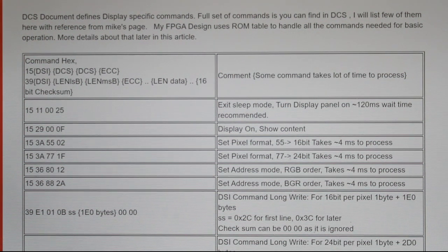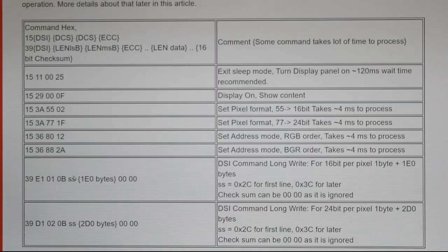But please make a note here, these four commands which I have listed here, they take 4 milliseconds to process. So it's quite a lot of time in terms of display. Please take care when you are changing display format or pixel format. Make sure you are waiting long enough for the LCD to process this command, or you will see weird behavior from the display, like display tearing.